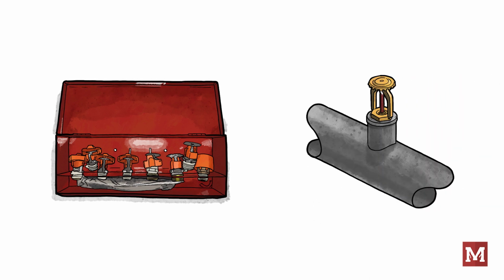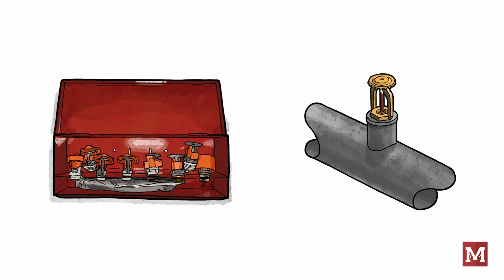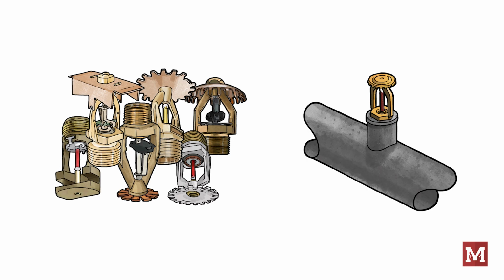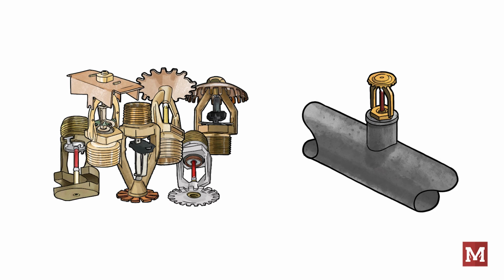Not all sprinklers are created equal, but every single one out there has a part to play. What we care about are the hydraulic properties of a sprinkler and the listing of the sprinkler. Whether we're calculating a sprinkler system we have designed or calculating a system after the fact to determine hydraulic adequacy, these are very important data points that we must know. For a sprinkler's hydraulic characteristics, oftentimes the most important bit of information is the K factor. Like we briefly discussed in the last segment, the K factor is a coefficient number that corresponds to the flow characteristics through the sprinkler's orifice. The larger the K factor, the larger the orifice, and vice versa. We need to make sure we have this correct.